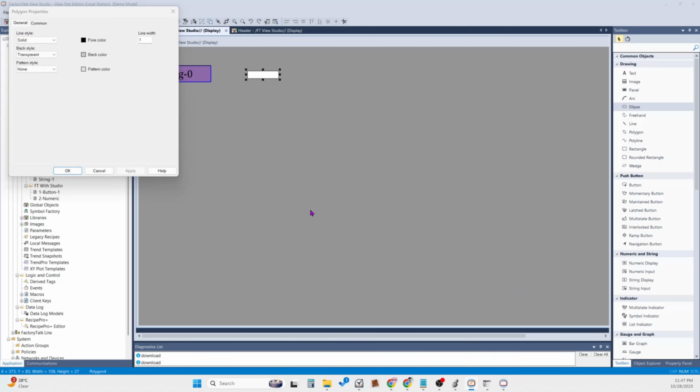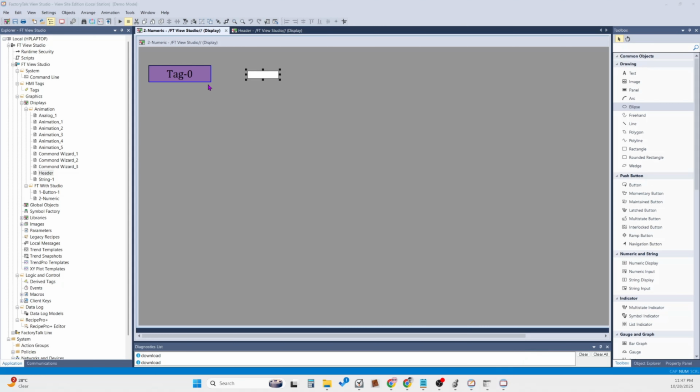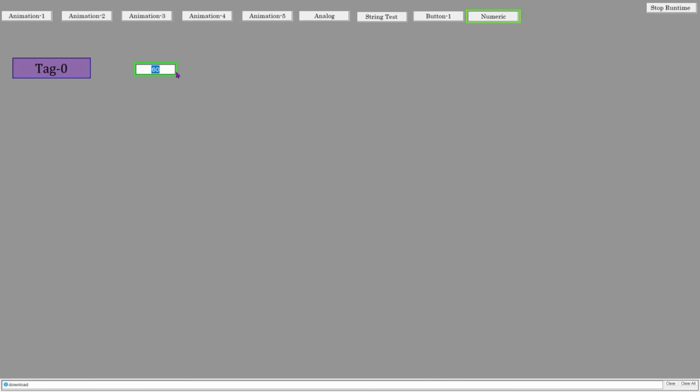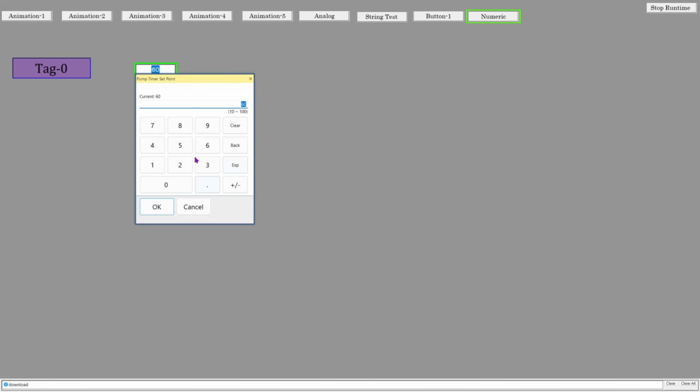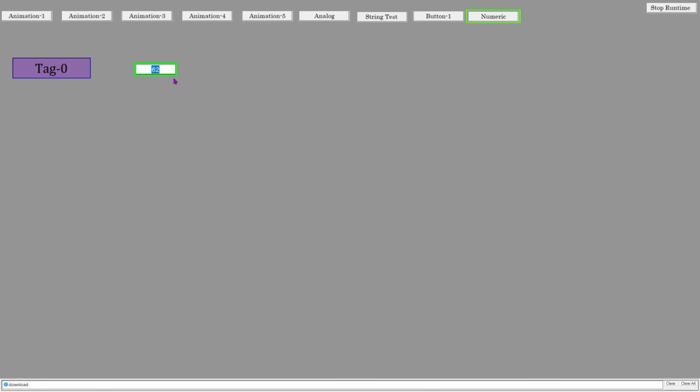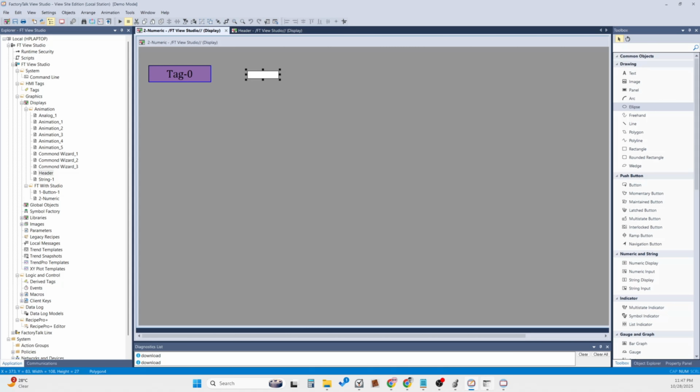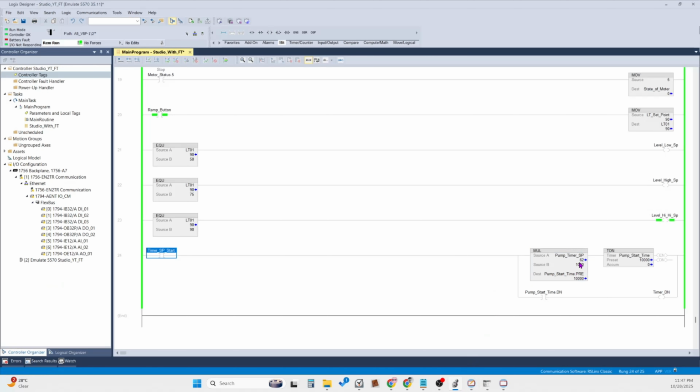Capture cursor. It is the capture cursor. That is the reason it is showing a capture here. If you enter 62, in 62 you can see green color. Not the capture cursor. On the back side you can see green color. It means the rectangle is showing. And what is the value inside the timer? The timer value is 62, you can see. The timer set point is 62.